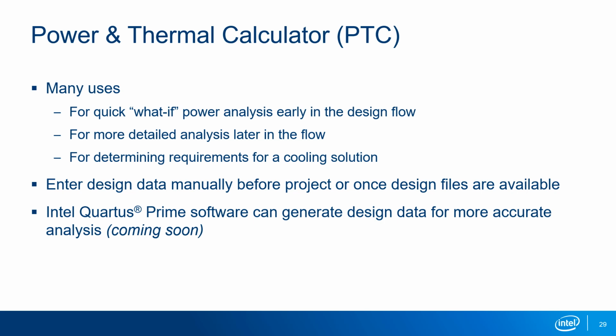Future releases of the Intel Quartus Prime software will be able to generate power-related information for your design that can be immediately imported into the PTC for the most accurate analysis. It is available in two flavors, the Quartus Prime integrated and also the standalone, in both Windows and Linux versions. Some of you may be familiar with the early power estimator known as the EPE, offered for previous FPGA families. For Agilex, we have it integrated into Quartus, making it much quicker and much more responsive.